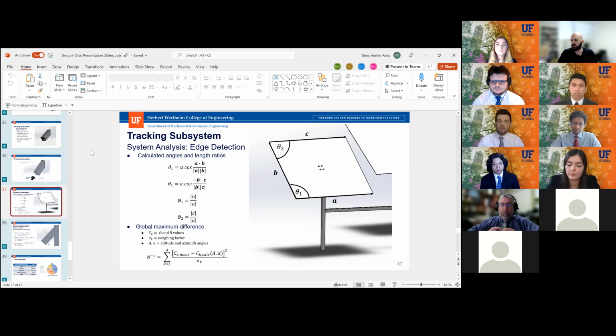So it was assumed from the customer needs that they could extend up to 100 meters from the tower. And so if you had a radial pattern, plenty will fit in that area. Yeah, so was the camera the constraint on why you kept all the heliostats at the same height? Because it seems like you could compact them together a little bit better if you had them at staggered heights instead of all at the same height. So the reason that we had them all at the same height was for the shading reasons.